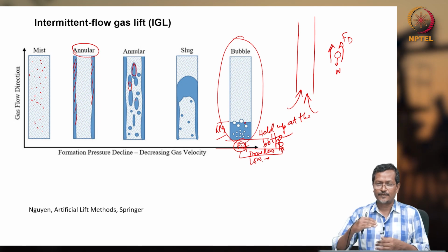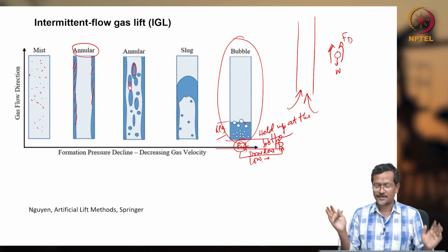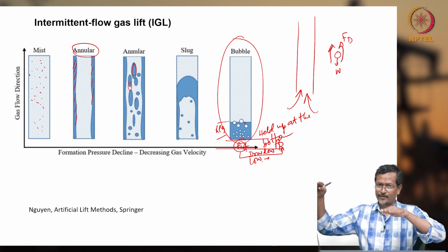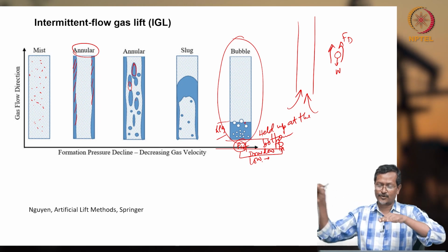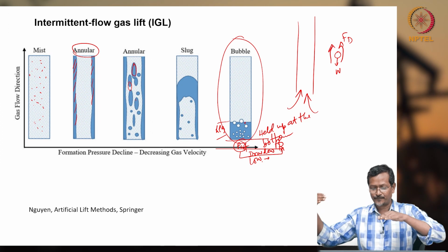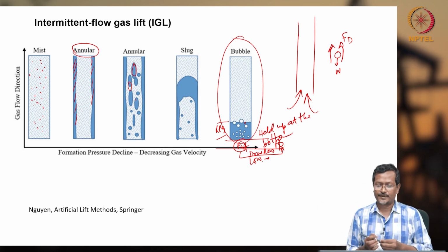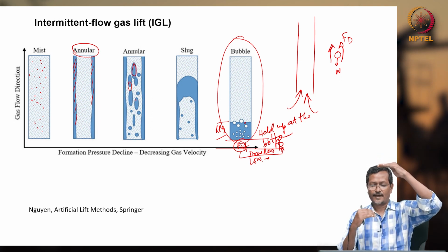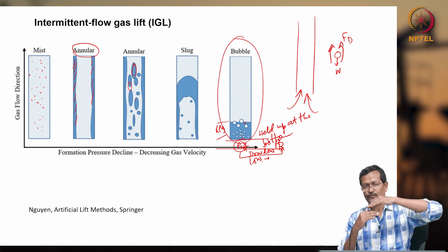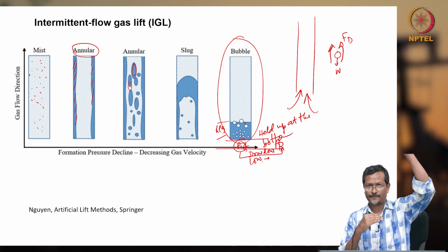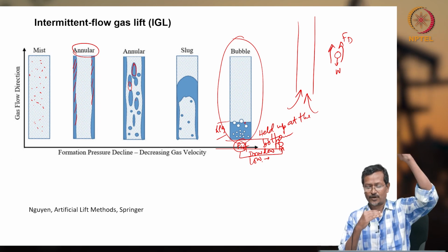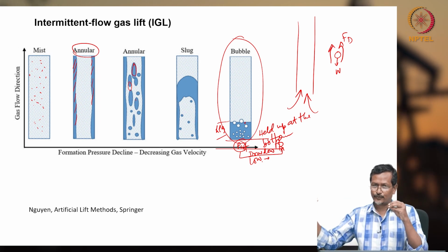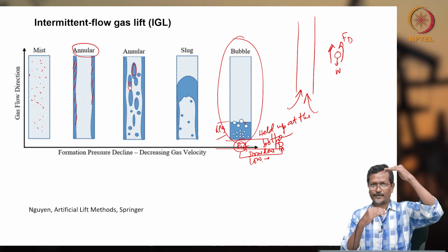So, what you have to do, you remove the liquid from the wellbore by any means. If you remove, again PWF or flowing pressure will go down and reservoir pressure is here, fluid pressure gone down. So, difference created, drawdown, higher difference created, again fluid or gas or liquid will enter into wellbore, it will move up, okay. And if you have higher liquid column height, it will be further obstructing this one, and liquid column will not move up to very high level, it will not create very high liquid column, because when flowing pressure, reservoir pressure almost equal, that time fluid or liquid will not enter into wellbore. So, the column height will be limited only, okay.